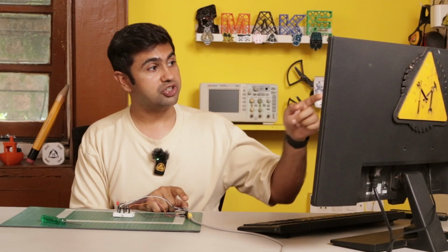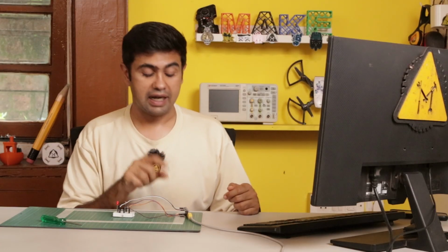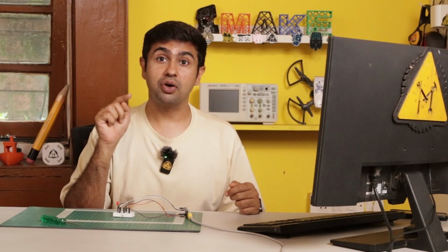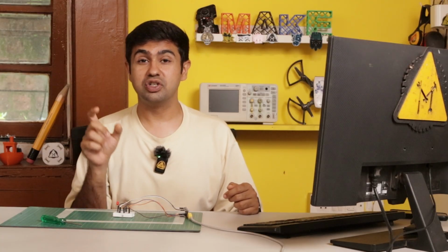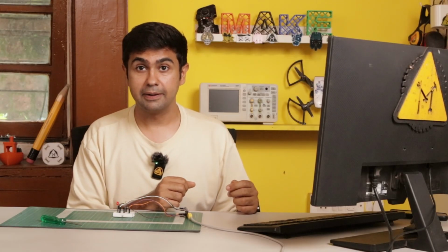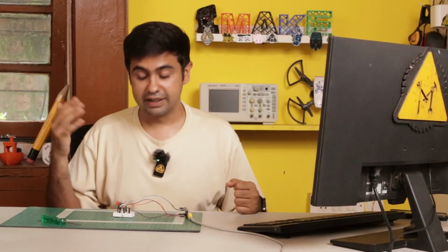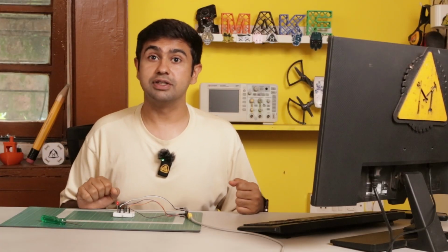And your output, which is the LED, is connected to the PWM. If you remember, we did this earlier as well, digital output. And over here, your range is between 0 and 255, which is an 8-bit processing of the output. So your Arduino is giving an output as an 8-bit processor, but it's taking an input as a 10-bit processor. So your range for the input is between 0 and 1023, but your output is only between 0 and 255. If you don't follow me completely, don't worry, we'll try and explain this in more detail in the course document, or your mentor can also explain it to you.